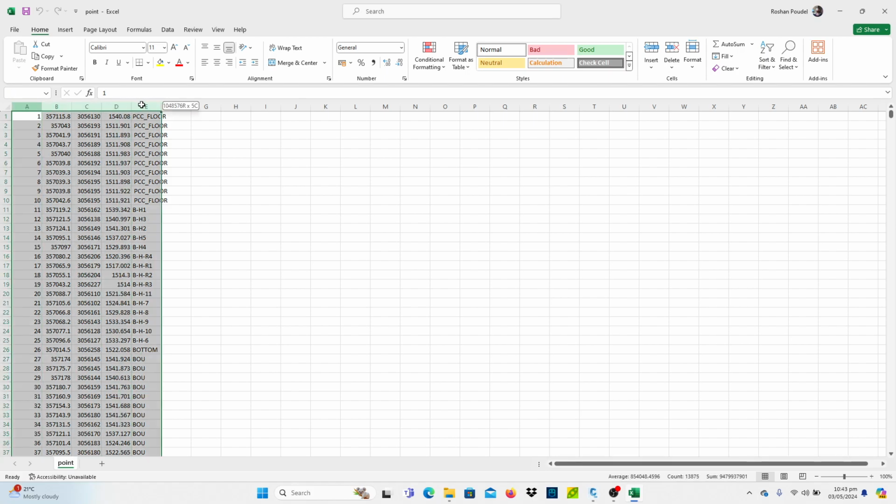These are usually extracted by fixing your stations by making an open traverse or a closed traverse, and then we have to make a gauge table, and after we have set the stations and know the exact locations, the spot surveying can help us to extract data as such. So this will be the serial number of our data in the first column.